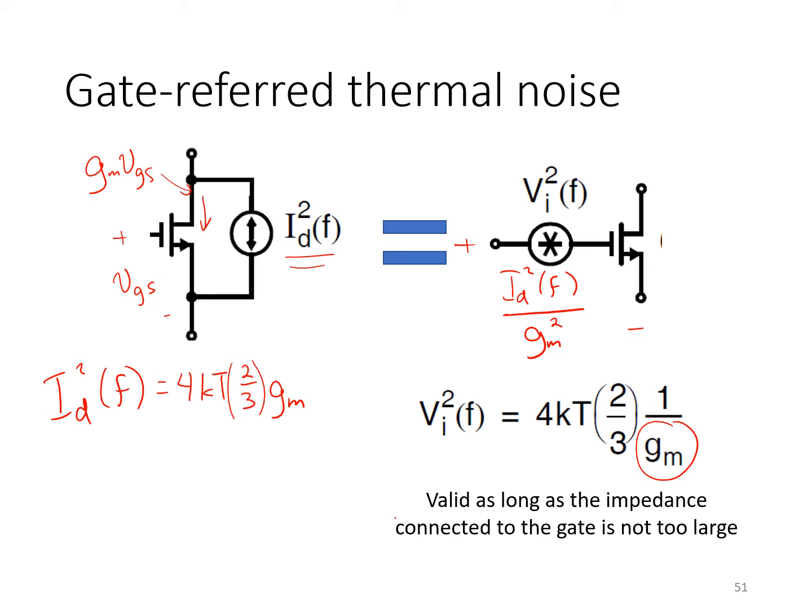But if the transistor is just being used to provide a DC bias, then the extra noise current is purely extra noise. So for transistors that are not being used to produce a signal current, but just to produce a DC bias current, then indeed we would prefer a smaller value of GM in general to give us less noise running around the circuit.